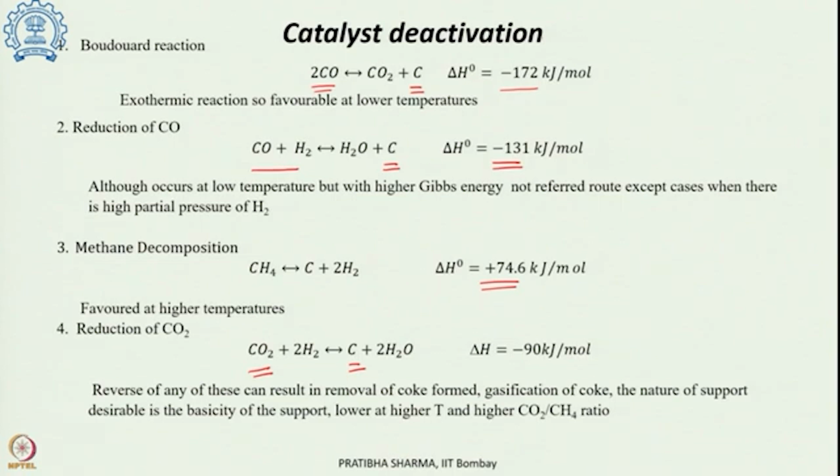The support can provide desired basicity, which instead of supporting carbon formation, like decomposition of the various species, can support carbon gasification. So, the appropriate support, catalyst and promoter use can reduce the carbon formation.